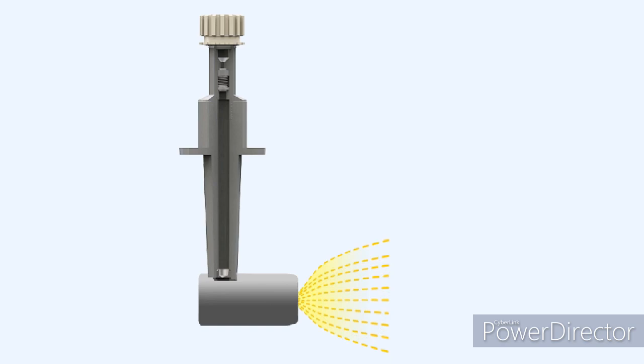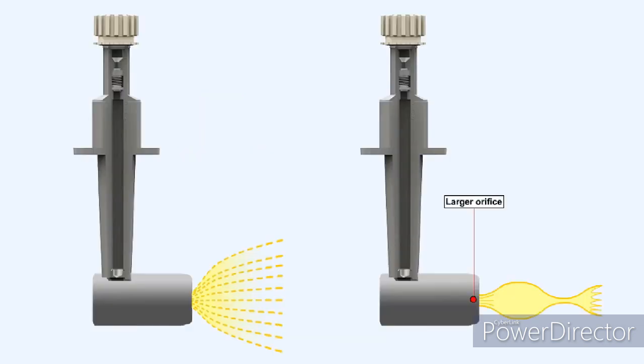Eventually the pump produces sufficient pressure to shorten the tulip until it touches the orifice. Only now is the fuel jet atomized sufficiently to ensure rapid burning. We've demonstrated then that a small orifice of fixed size will provide a finely atomized spray at high fuel pressures. However, when higher volume fuel flows are needed through larger bore nozzles, the pressures required from the pumps to provide that finely atomized spray become unattainable.